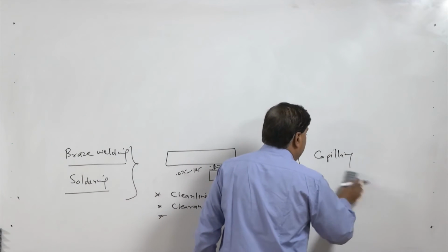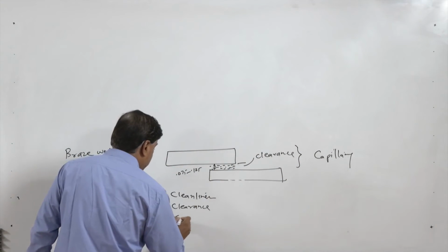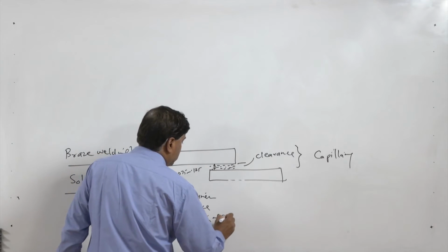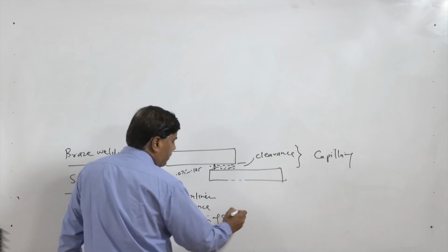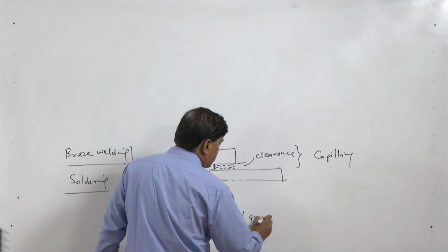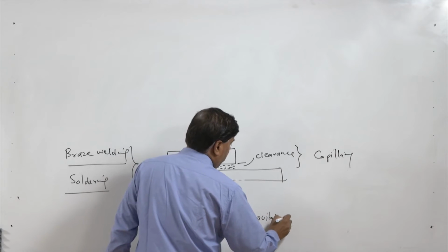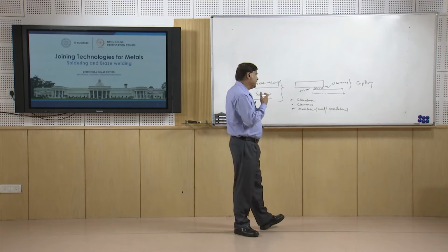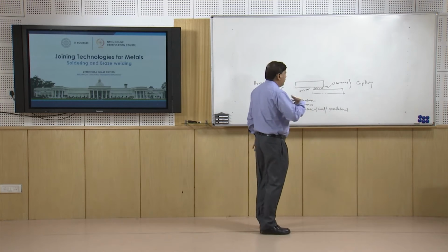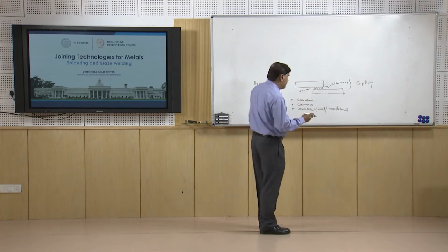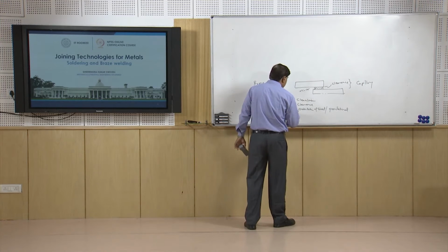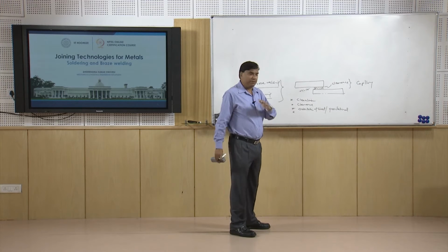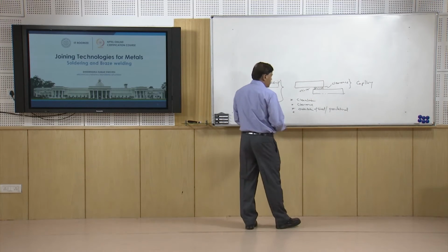So, indirectly we can say the orientation of the plates or the sheets matters, and this effect is primarily due to the gravitational force. How gravity is assisting or resisting the spreading or distribution of the solder will determine the uniformity and ease of spreading of the solder.